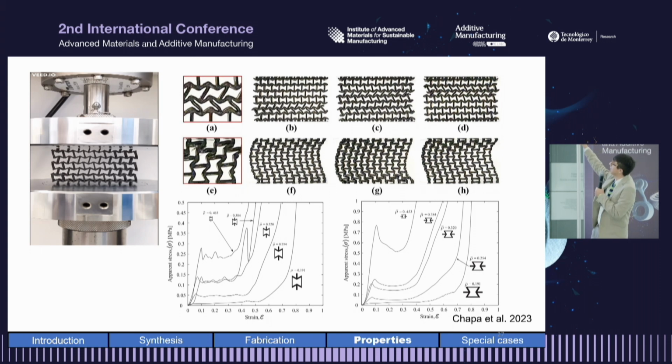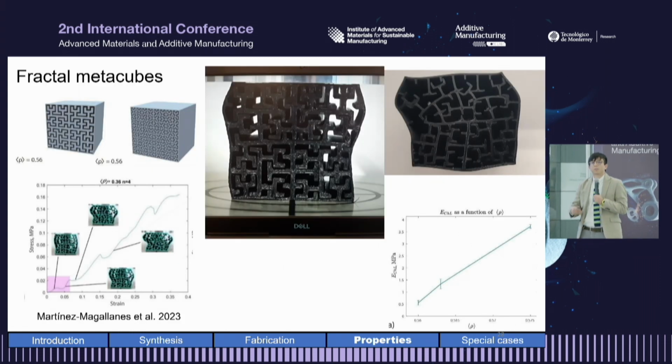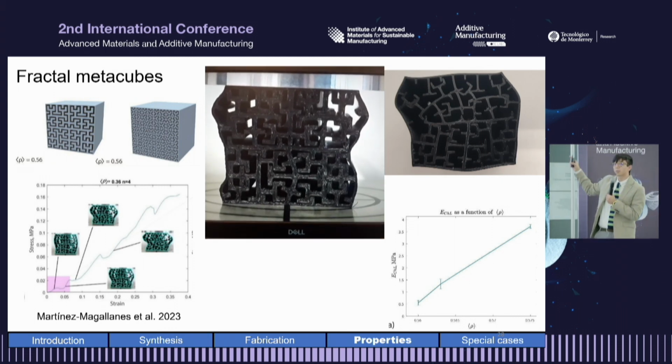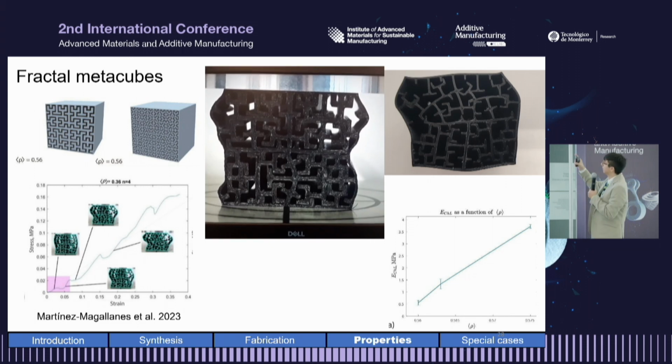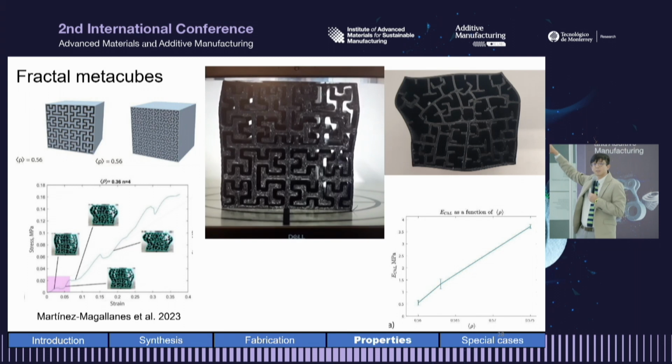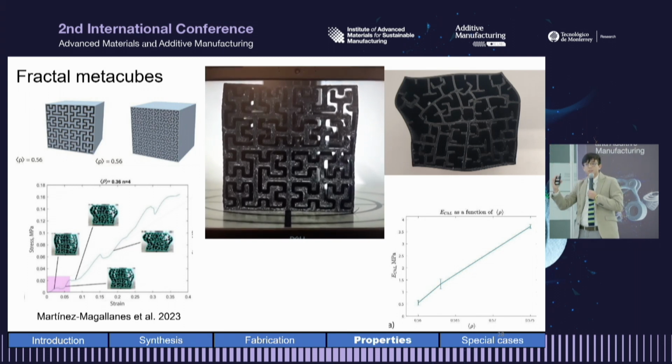One of them has a macro buckling, and the other one has some micro buckling at the cell wall level, although both of them have the same amount of material. So you are not only controlling the overall effective property, but you are controlling how these guys respond, how these are going to be deformed. Like in this case, again, we have some buckling, but because of the fractal design, we can control when that buckling is going to stop using the same parametric definition of the curve.